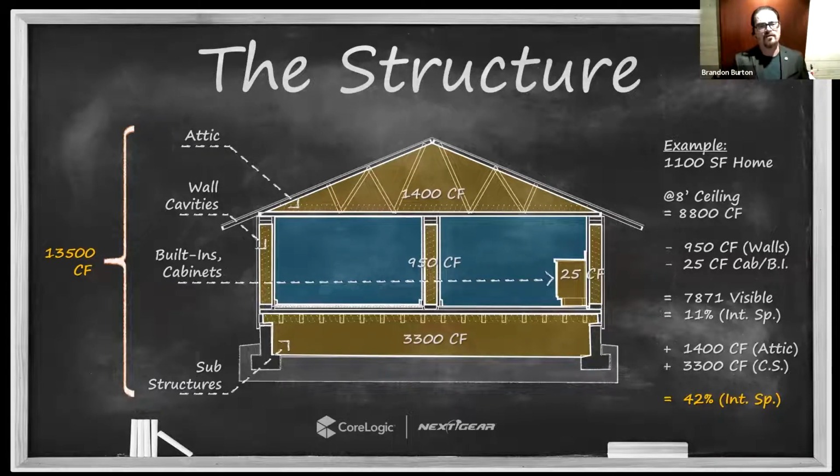So today's session is an extension of that. We're going to take that same line of thought and move into substructures. Substructures can include a couple of different spaces. They can be basements, finished or unfinished. They can be crawl spaces, really any area that is beneath the main floor living space of a structure. These spaces are unique in terms of the way we approach them for drying. They're typically unique in the nature of construction and the types of building materials that we encounter. They present unique challenges for access to outdoor air and ventilation as appropriate. So lots of unique challenges they bring that we want to unpack today.